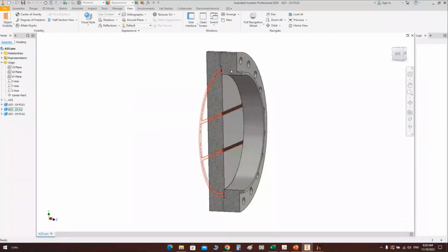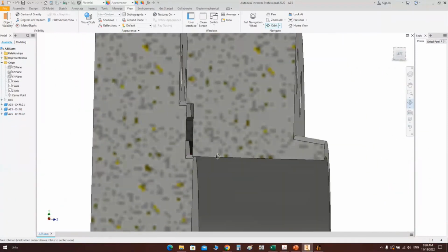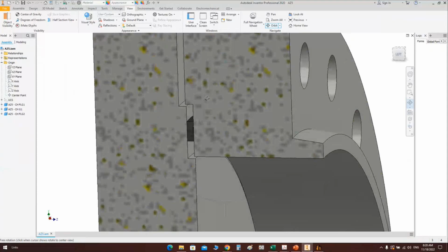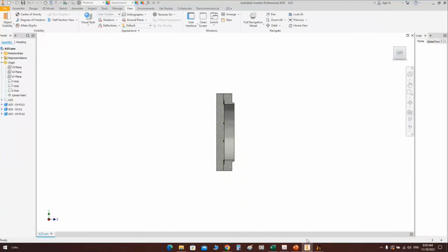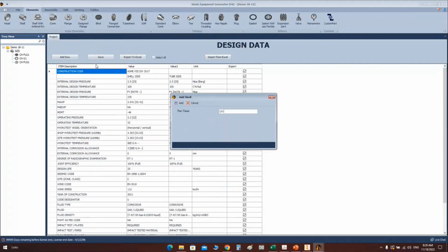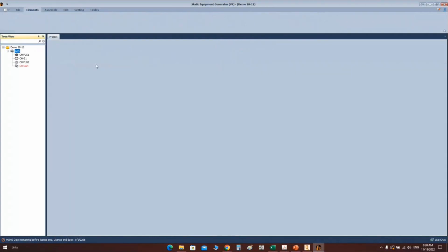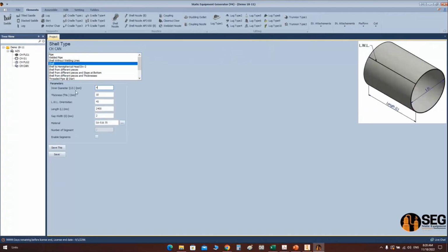Here we have this gasket. Here we have this connection like this. Okay, the cover gasket and the body flange. Now let's add a channel. So from here, it's channel 10. And here from this can, let's select shell type, define the inside diameter, the thickness, the longitudinal welding line orientation, and the length of this can, the weld gap, the material of this can.